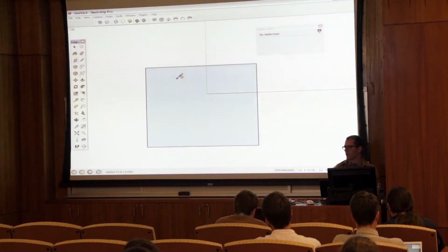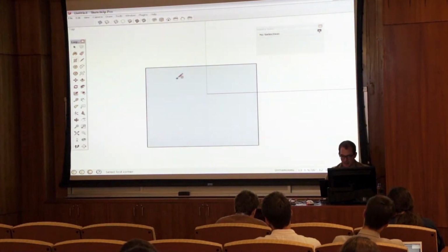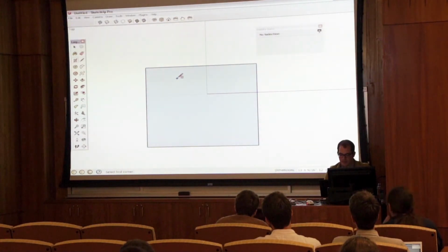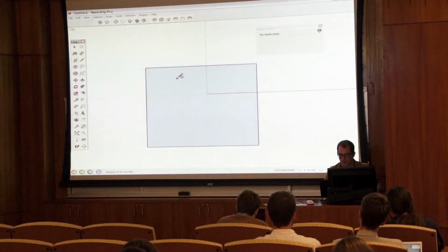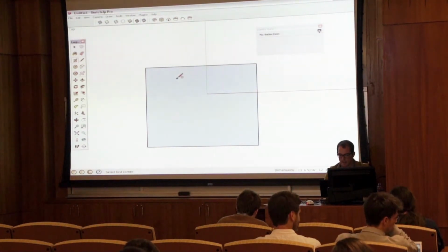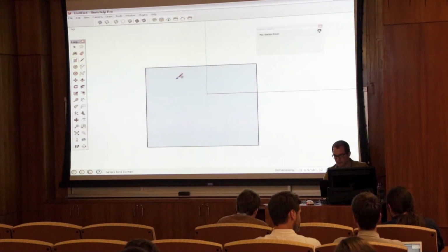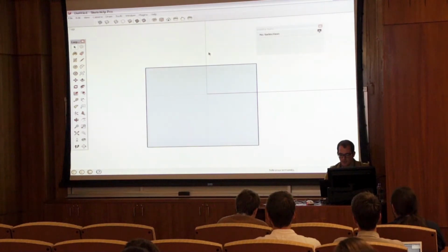One thing when you're working on a laptop with SketchUp, or even with the mouse, my left hand's always on home row. So my left hand's always on ASDF. Specifically, a lot of keyboard shortcuts are off of there, like R is rectangle, E is erase, T is tape measure. I make group as G. The space bar is your select tool. Q is to rotate. Just sort of weird.